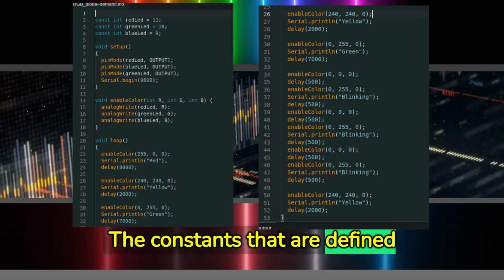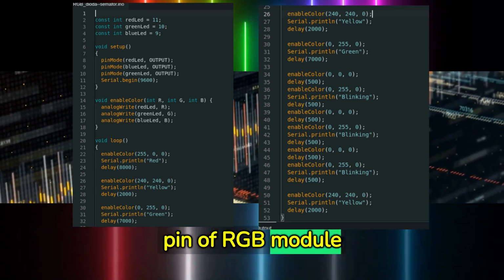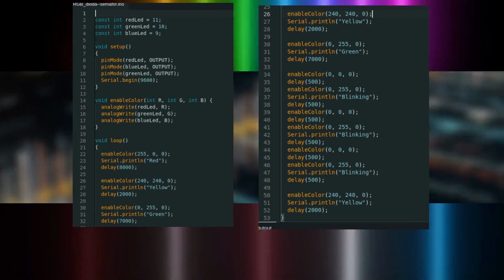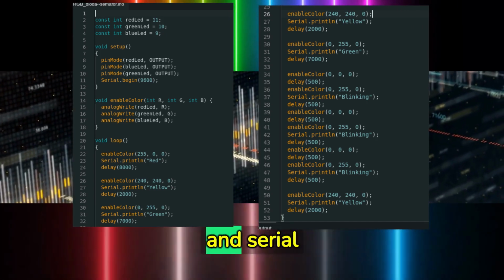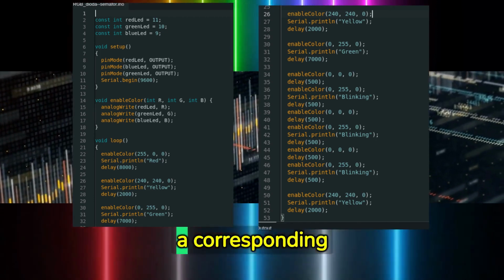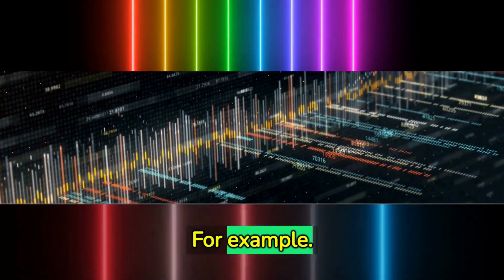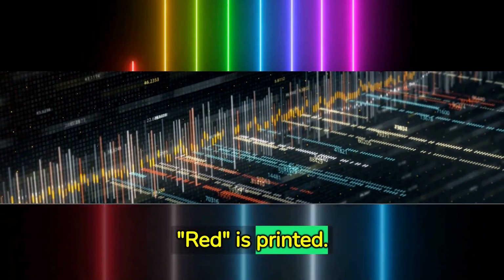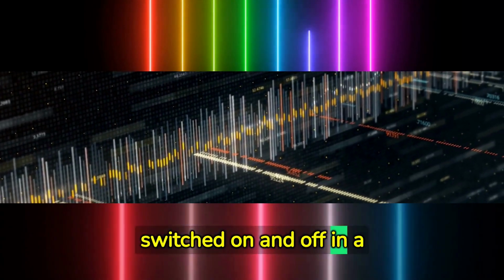The constants that are defined in the program are the pins to which the R, G, and B pins of the RGB module are connected. In this case, they are pins 9, 10, and 11. The setup function only defines the output modes of operation of these pins, and serial communication is enabled because when each of the lights is turned on, a corresponding message is printed in the serial monitor. For example, if the red diode is on, the message red is printed. In the loop part, the LEDs are continuously switched on and off in a defined sequence.